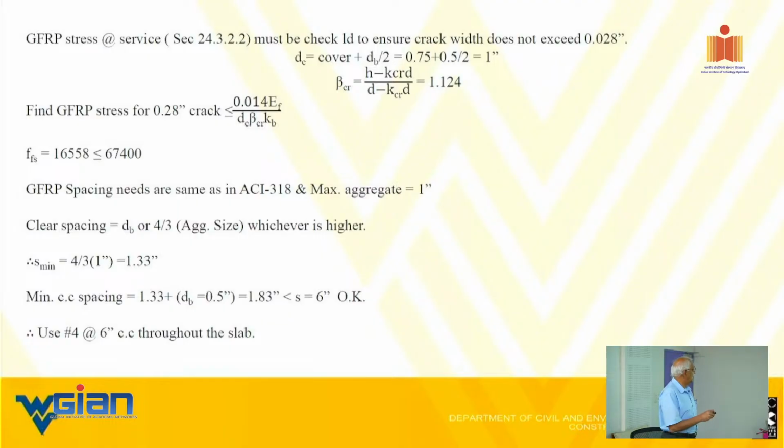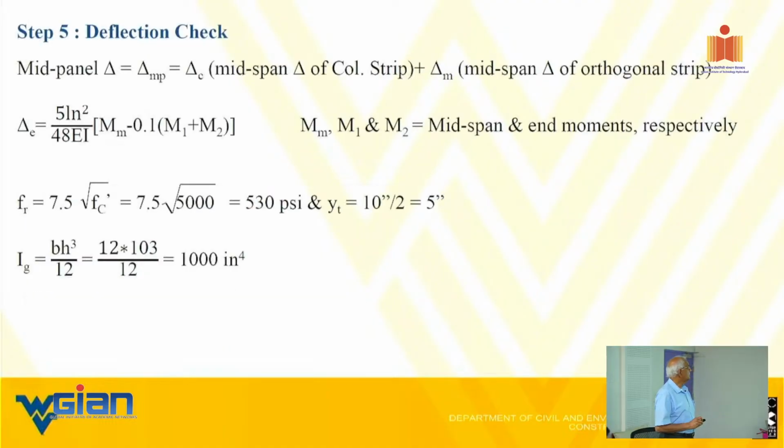So that is how you go through this, and ultimately the spacing that we came up with earlier seems satisfactory. So now we are talking about deflections. Any deflection, you know what that is? That is your WL^4 over 384 EI, but written in a moment form. If you multiply that with L^2 over 8, you get exactly your WL^4 over 384 EI written in moment form. And we have positive moment, and these are the two midspan.